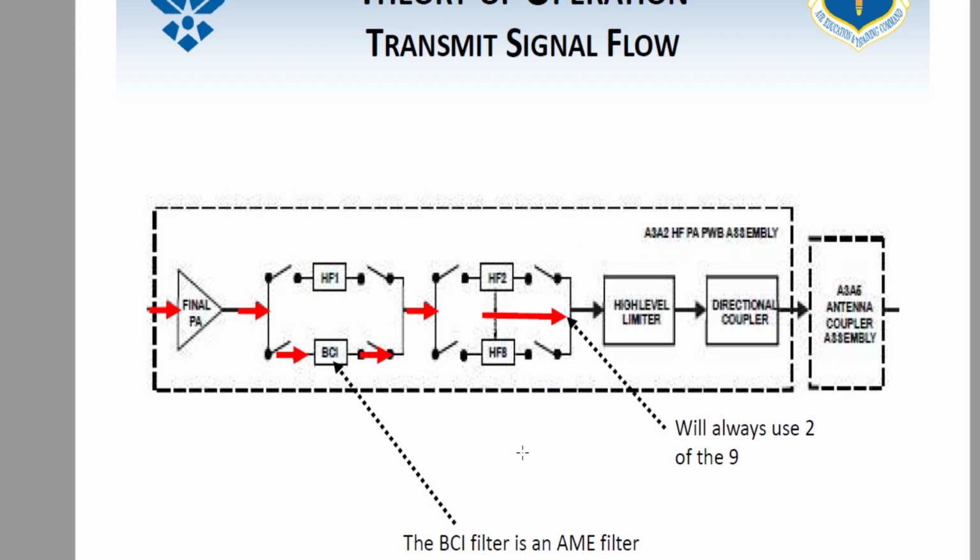All right, so BCI, like you were saying, that's that AME mode. AME mode is used for talking to AM radios. The reason we can talk to AM radios is because it puts a little bit more of the carrier into the signal itself. Normally with single sideband radios we suppress that carrier. We don't want to use it because it takes up power inside of our radio, right? Because in an AM radio, that takes up 2/3 of your power just to transmit that whole carrier all the time, and we don't do that with a single sideband radio. So right now we're introducing a tiny little bit of that back in so we can talk to those citizen band, those commercial band radios, those things that truckers and stuff use, or hikers. If they're out in the wilderness, they can use that.